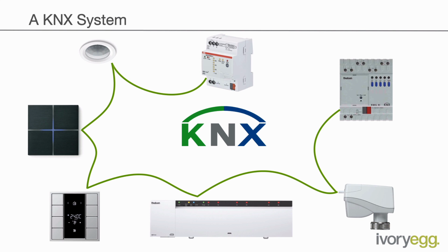In this example we can see a power supply at the top which powers the bus. That's from one manufacturer, and then we've got a PIR from another manufacturer. That PIR is going to detect motion, it might be reading temperature, then it'll be sending a signal onto the bus saying there's activity. That signal then can be picked up by a manifold controller, which is at the bottom of the screen, or a lighting relay. All these different products can all respond to the different messages happening on the system.